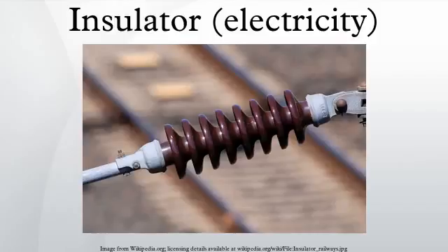The advantage of this design is that insulator strings with different breakdown voltages, for use with different line voltages, can be constructed by using different numbers of the basic units. Also, if one of the insulator units in the string breaks, it can be replaced without discarding the entire string. Each unit is constructed of a ceramic or glass disc with a metal cap and pin cemented to opposite sides.